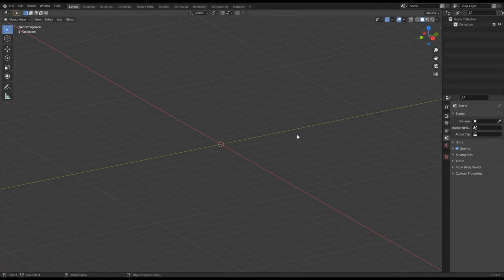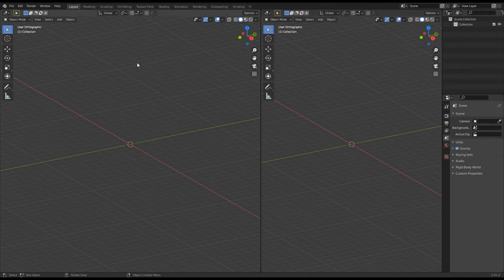Now, while we're talking about the layout, there are a couple more useful things to know. One is, we got rid of this window down the bottom. You can actually split a window as well. So again, I go sideways here until I get the double arrow, right click, and then it's a horizontal or a vertical split. Vertical split, take it to wherever you want, hit it, and now you've got this 3D window split into two.